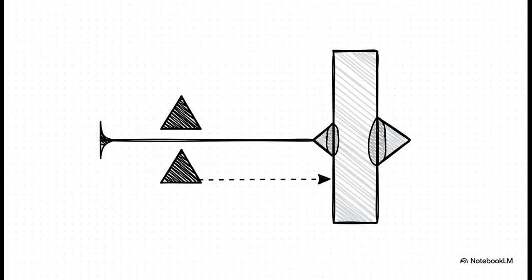Now, this is where the real genius of the system kicks in. That reference line acts like a divider. Any symbol or number placed below the line applies to the side of the joint that the arrow is pointing to. We call that the arrow side. Anything placed above the line applies to the other side of the joint. It's such a simple rule, but it solves a huge communication problem instantly.